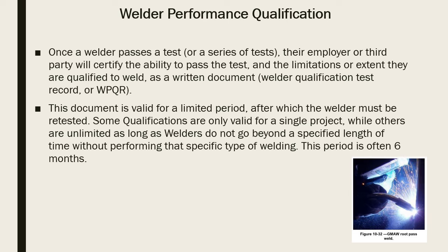So this is where you get into keeping track of your welders and whether they have used the process. We used to keep a log, a continuity log. So a welder would have to weld with a specific process, let's say flux core. Every 6 months, I would need to see that welder weld with that welding process. If he leaves the company, he loses his certs. If he doesn't weld with that process within 6 months, he loses his certs. And I think we had everything set up to do it every 4 months so that even if I missed something, I would still get it on my continuity log. So we kept it a little shorter.